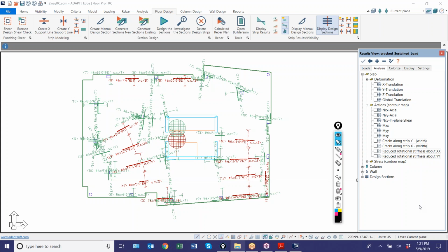But in terms of a long-term multiplier, there is a correction factor that is using the contribution of compression rebar. Our long-term multiplier doesn't consider that, but the actual cracked evaluation of every design cut considers the rebar only for the calculation of the cracked moment of inertia.